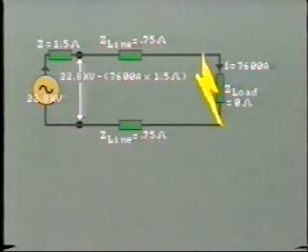That is 22.8 kV minus 7,600 amps times 1.5 ohms equals 11.4 kV. We know in practice that it is all a lot more complicated than this. We have 3 phases to worry about, and moreover, the impedances may be at different angles and therefore would have to be added vectorially. But the conclusions are very clear.